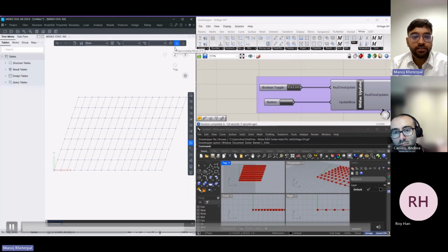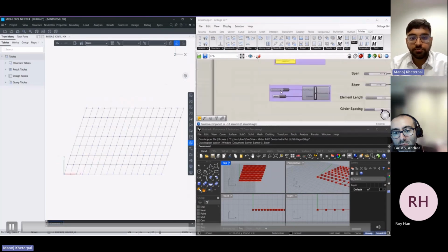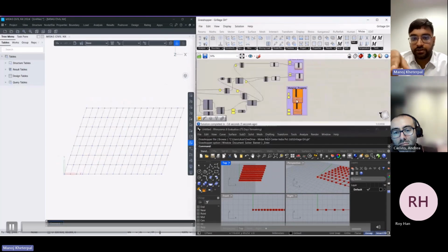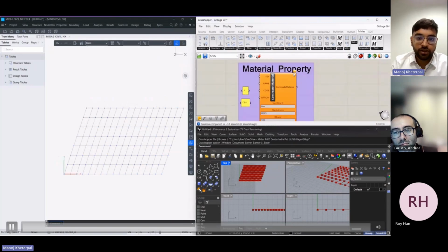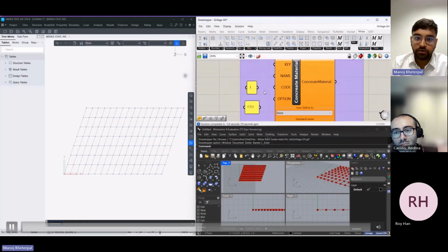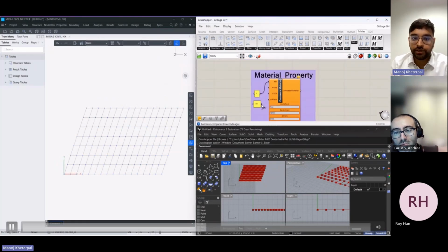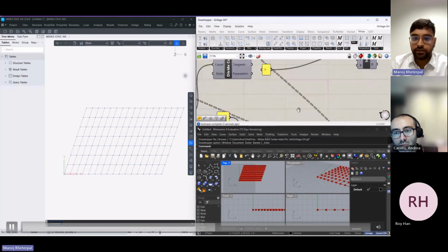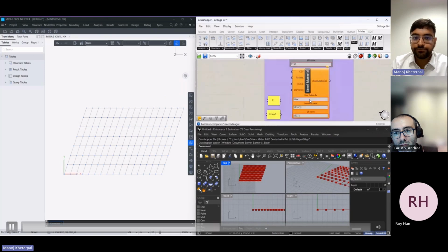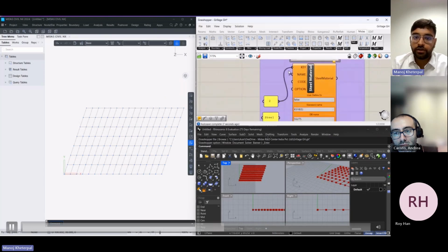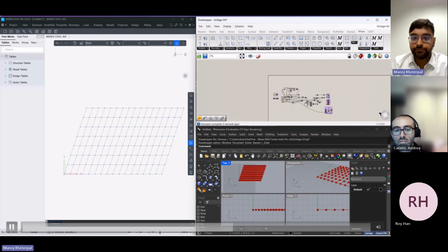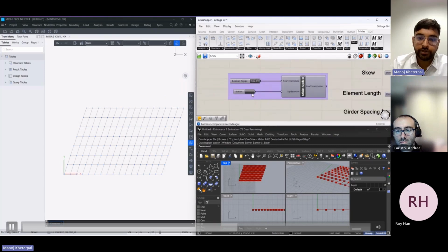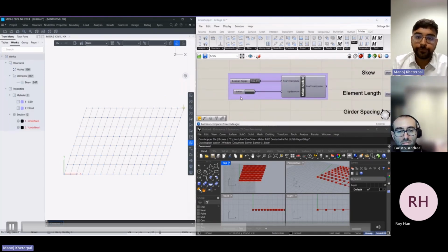And then, yeah, now you can just simply update, because those line-like curves are directly connected through the beam plugin for the Midas. And now I can just plug in the cables inside the name and the key. And then I can do a similar thing for the steel property that needs to be defined. Yeah, so now you can get that. And then if you press the update button here, all these material properties will be defined here.